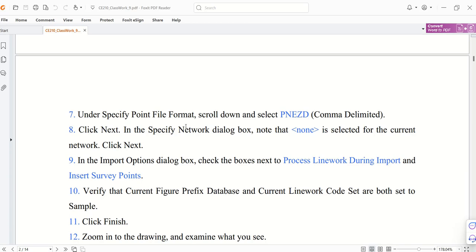For example, imagine you have a humid area. You survey the limits in your land survey. You survey this limit, and you say this area is humid. So you circle it, and if you are working in a classic way without informing about the description keys of those points, they will appear as points. And you should come back and link them with a polyline and say that this is a humid area.